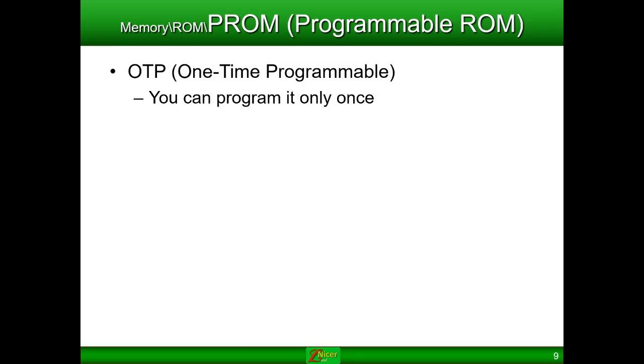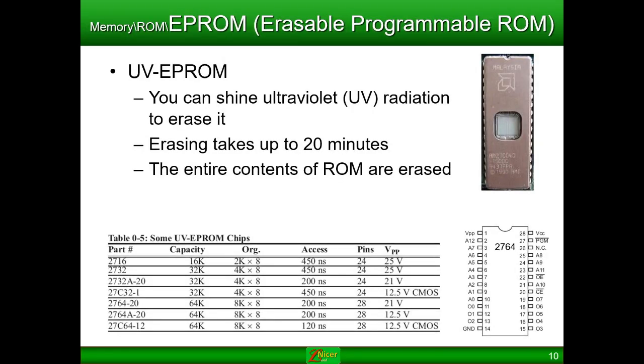So once it is programmed, you cannot change it. This is EPROM. As I told you, it is erasable, but it takes a long time to be erased, and of course there are chances of failure as well. So it is not suggested that a normal person should erase it. It uses ultraviolet radiation to erase it. Erasing takes up to 20 minutes, and the entire contents of the ROM are erased,